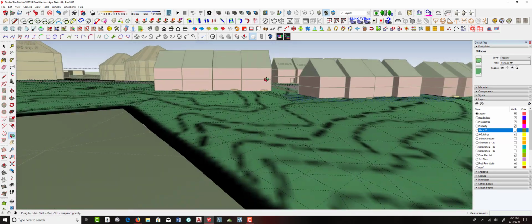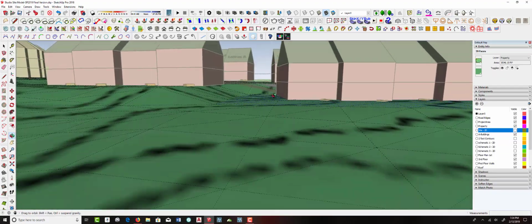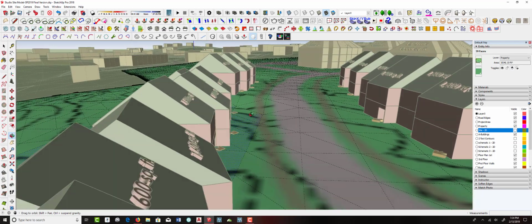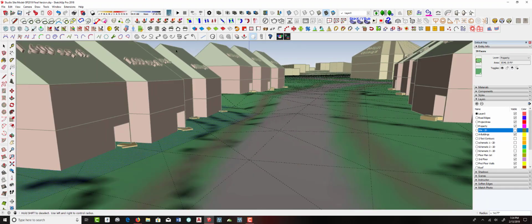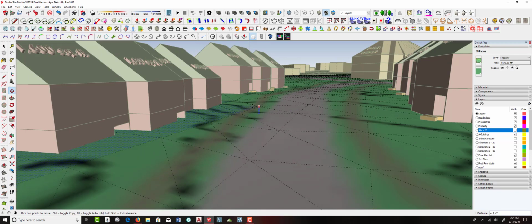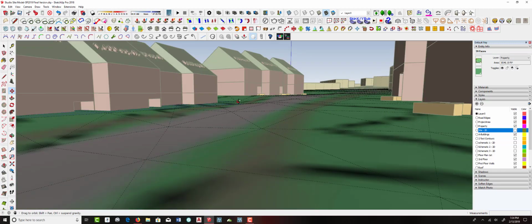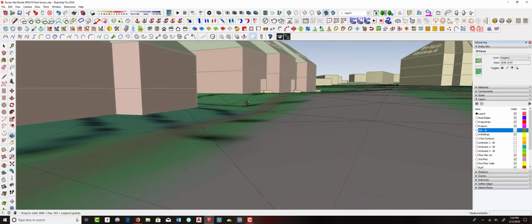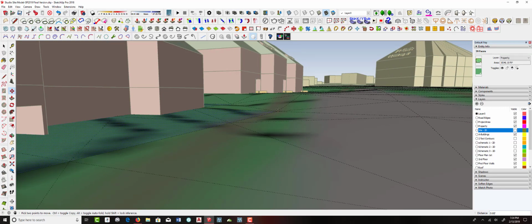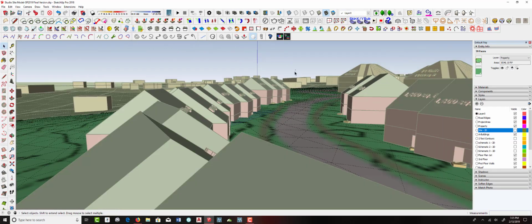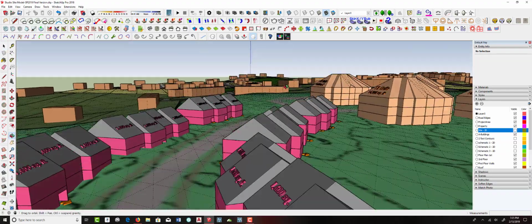And you can see now it's created that slope between there, but it's also created this big drop on the roadway. So before I get rid of that selection, I'm just going to use SketchUp's normal move tool. Click on that, tap the up arrow, and I'm going to say, okay, I want that to be a little bit lower than that last elevation, but not quite as low as it's showing right now. So I'm going to move that up just a little bit. Once I do that, tap here, just jumped out of there.